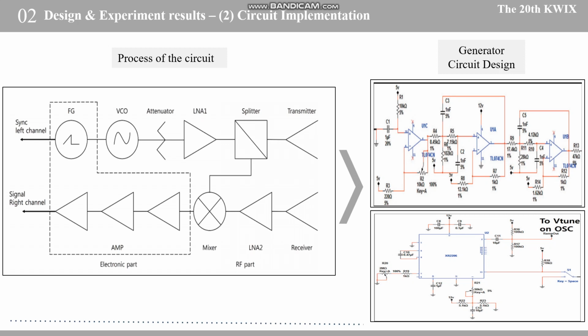The signal received at the receiving end has a very small power, so to increase the gain we purchased a better TQP3M9036 LNA chip and manufactured a circuit on the substrate to increase the received output to 20 dBm.